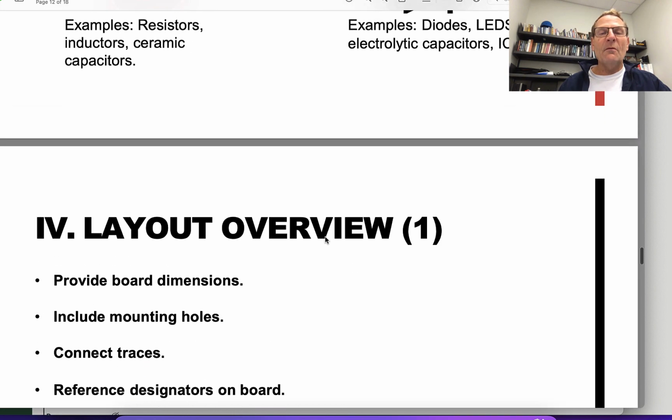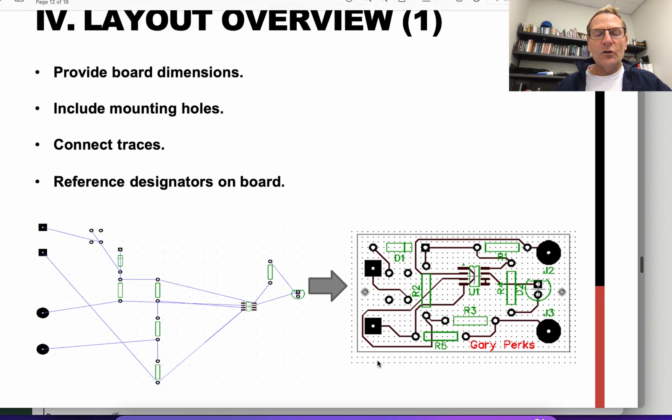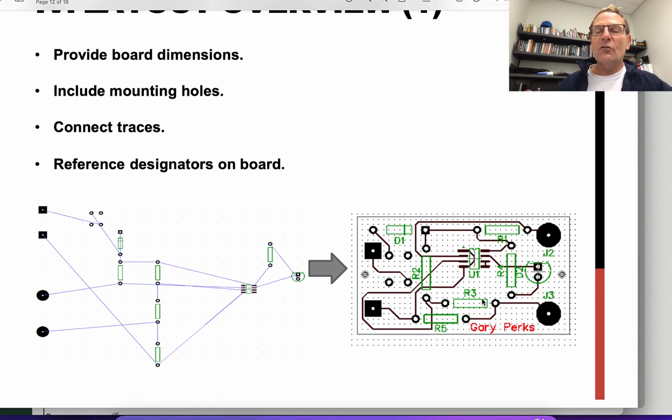Now remember, the electrical schematic is a series of symbols that represent the way that an electrical circuit will be connected. And now we can actually create, and you will create, your own electrical layout. That means that these components will be moved around by you physically in the digital space to different locations so that they fit nicely on the specified amount of room that we have for our circuit board. In this case, it has to be a very small circuit board because it has to fit into one handheld continuity tester device. So once you start moving components onto the board, again following the steps in the tutorial, you will see this start to come alive.